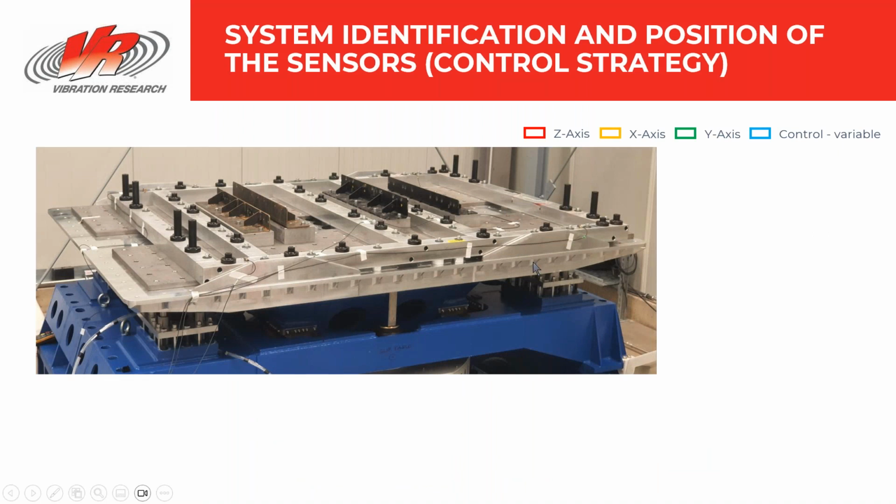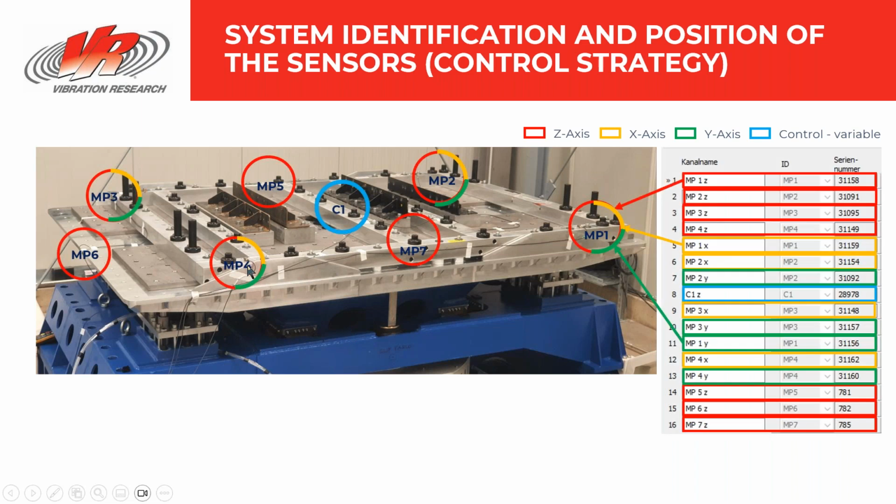Here's a vibration fixture on a large battery pack. Just to show you the different measurement points and checkpoints that might be on there, with different control, where we're looking at the variation and how to control this fixture and the different variations in acceleration levels. If you don't do this mapping process properly and you start controlling in the wrong areas, you're really going to start over testing or under testing. You can simply get completely different results by controlling in the wrong position. So you really need to understand all the interfaces and how they're varying with amplitude across the frequency range.